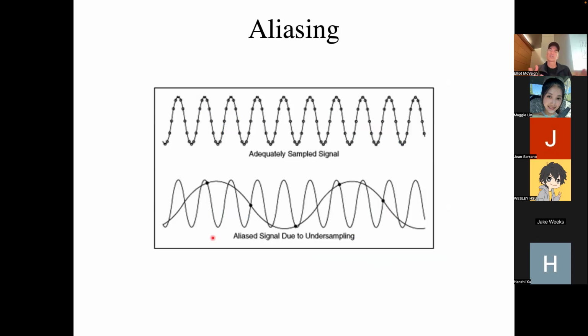So this undersampling phenomenon can lead to something called aliasing, and that's when these replicants of the Fourier transform get close enough together, they start interfering with your visualization of the function. And here's a very visceral demonstration of what aliasing is. If I have a clean signal, this is a very clean signal. It's a sine wave that's just going with a certain frequency.